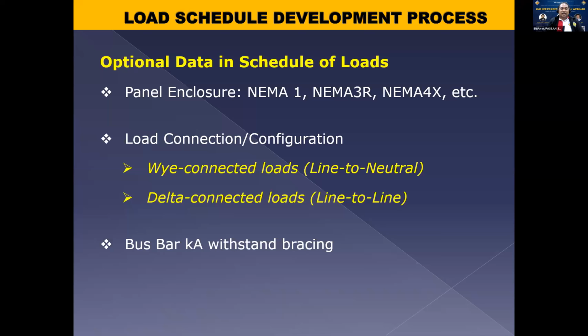And then, additional optional data is the bus bar kA withstand bracing. Ang value nito is for manufacturers again na dapat yung mga bracing nila sa mga bus bars nila are rated for certain kiloamps na fault, no? Para it can be assured na during faults or during short circuits, properly braced yung mga bus bars natin, hindi yan masisira, no? Kasi malaking force yan, yung short circuit natin, mechanical force yan eh, no? Magnetic forces are at play during short circuits, no? So dapat they have to be braced properly na hindi yan masisira.